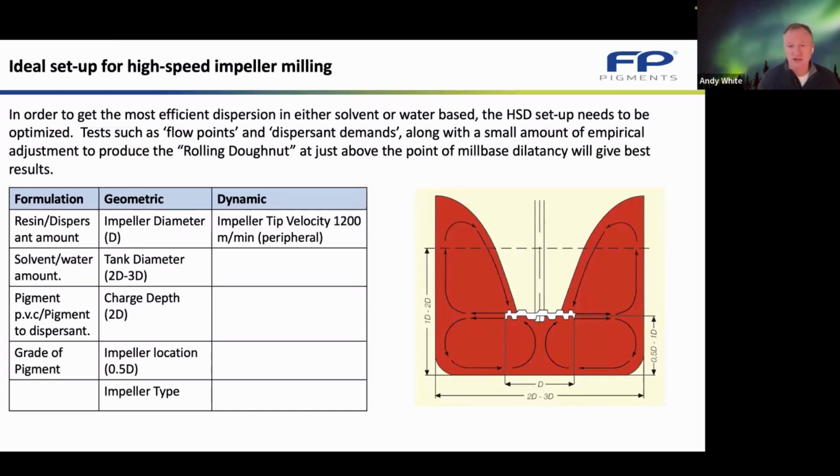That's not the reason for this part of the lecture, but I just want to make sure that everybody understands. If you have a dispersion problem with titanium dioxide, it's very likely your mill bases are too low viscosity, or your impeller's too low, or all of these things add to the performance you're ultimately going to get from the titanium dioxide if you do them properly and understand what's going on.